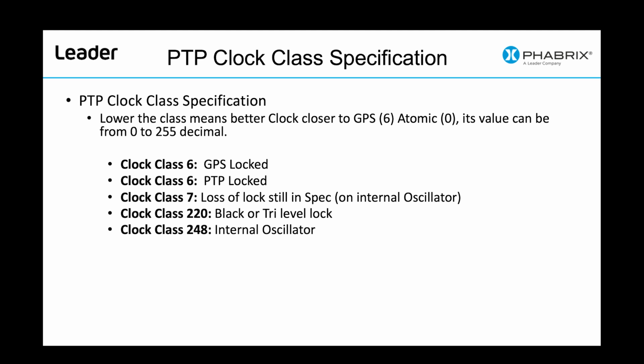So you can see from that GPS is going to give you a far superior accuracy, because we're down in the nanosecond range, versus looking at Blackburst or even a 1 ppm clock that's an internal oven controlled crystal. But they work perfect. That oven controlled crystal, we have TV stations that run the entire TV station off of that forever, and it works perfect.